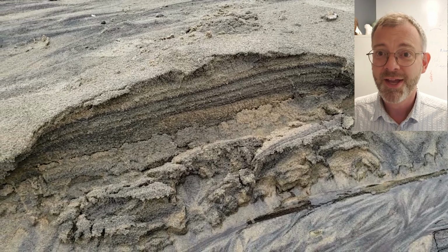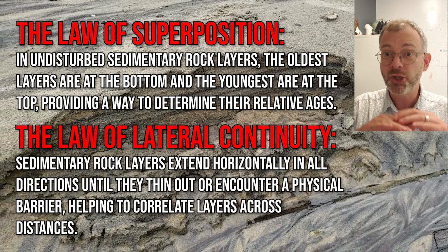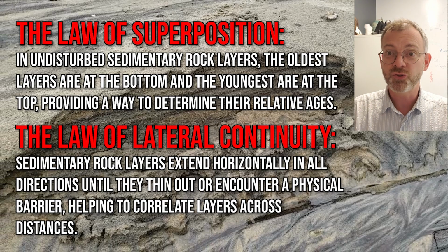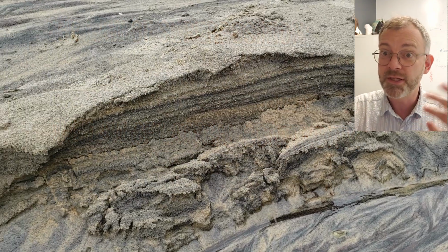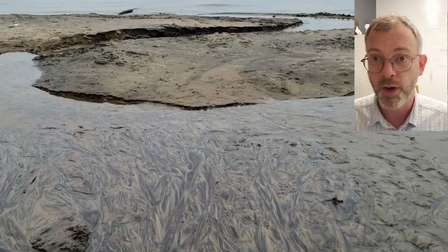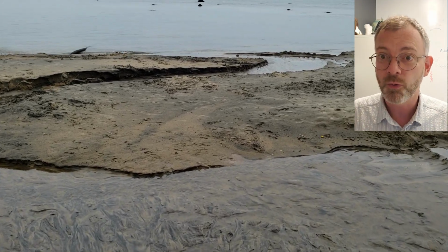One of our laws of superposition and a law of lateral continuity. Those horizontal beds are continuous unless disrupted by something else. Now, they could be disrupted by movement of the channel and deposition in a different area of the channel and so on. It allows us to consider those continuous layers within the channel.